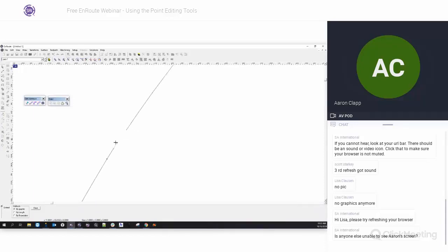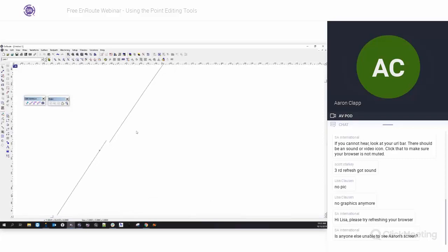There's an obvious arc to this line, and so as I move this along, it's going to follow that same arc path. And so I can move this up and down like that. I can also do it by length if I want, or by boundaries. In this case, obviously, I moved the lines around so they don't match up really, but you can tell it's trying to snap my cursor to that. It gets stuck right there because I have my snaps on. So you could use this to snap up to a line real close if you needed to.